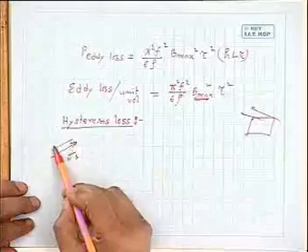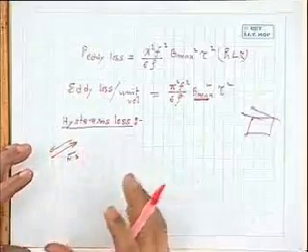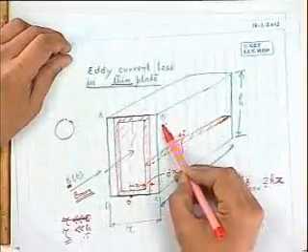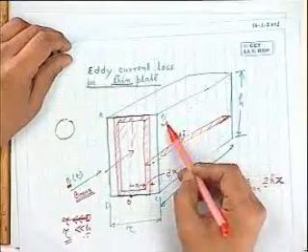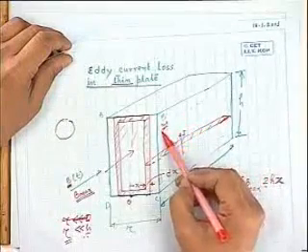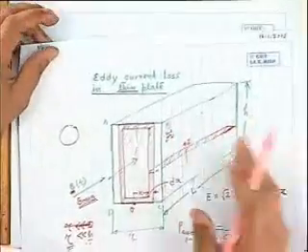The external field, whatever you apply, the molecules will try to align along that. But that field itself is changing its direction. So each molecule or domain will try to align sometimes, if you look at this diagram, suppose this is the flux, sometimes all the molecules will be north-south like this. And in the other half cycle it will be just opposite. It will as if rotate like that. That way the domains or molecules get changed every half cycle.